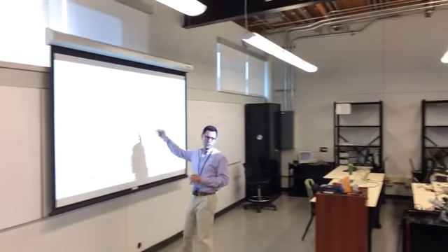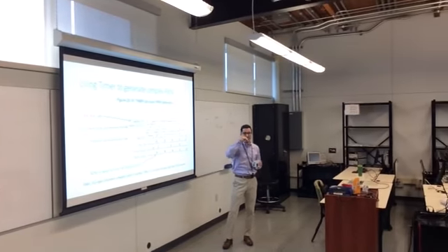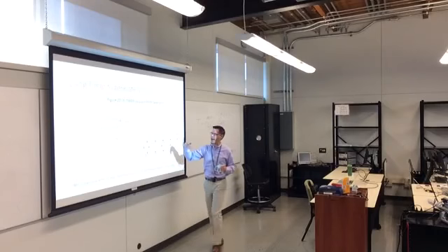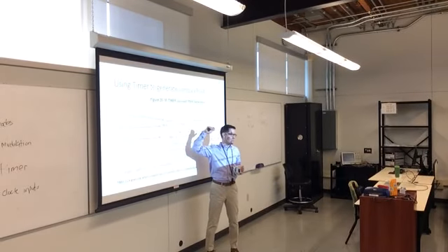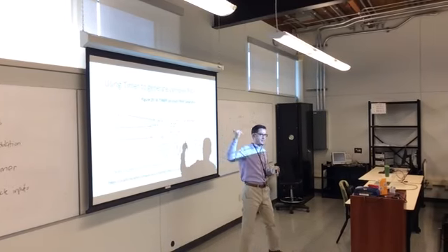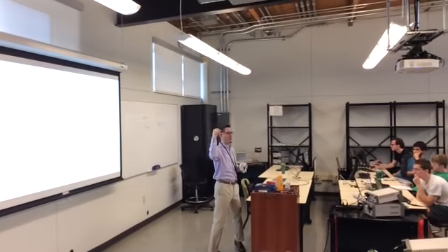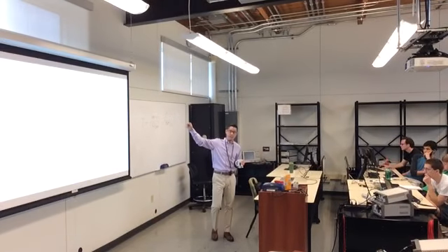So let's say I'm trying to copy a waveform. I could have another timer that is timing how long it's low and high, and then I could automatically update it to here or here. Yes, I can't tell you for a fact which ones, but generally, yes. That's why these are memory mapped: other devices can then write into them. Anything that can write to memory can write to those registers.